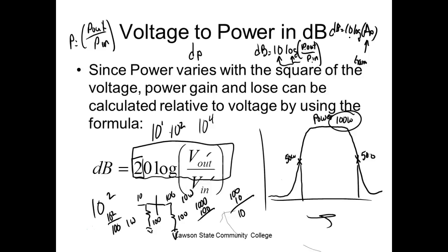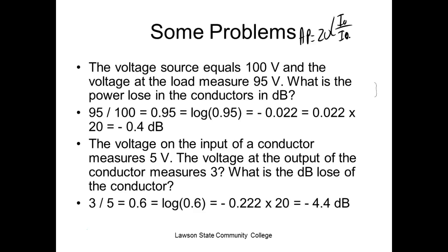But if you can measure, of course, you'd have loss. So if you can measure the output of your antenna and the input of your TV, and then measure it with voltage, then you would get the loss of your cable, and it would give you the power loss, right? That makes sense. But you have to measure it on the 50 ohm side. So you measure it on the 50 ohm side, and then at your TV, that would still be on the 50 ohm side, and you could calculate, huh? Where you screw the coax in. Are we okay?